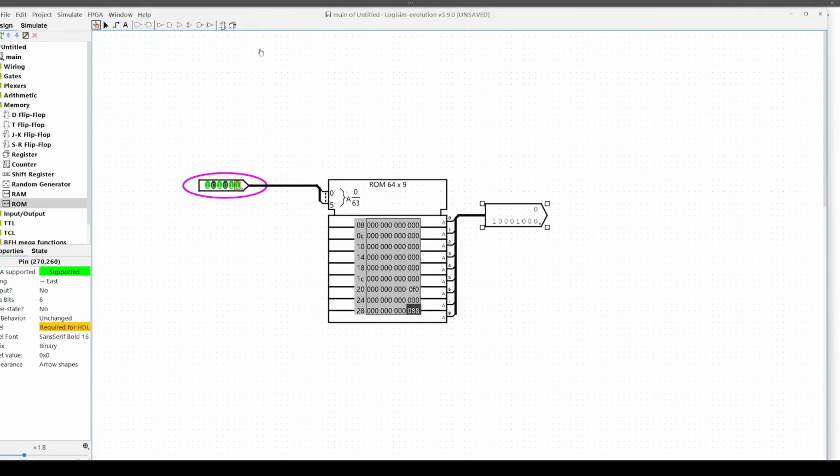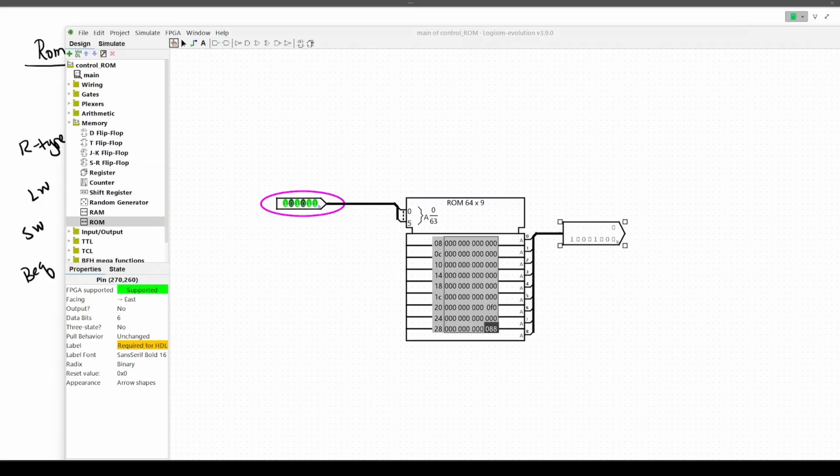As you can see, we have implemented our control unit. Very simple. No need to stress about gate implementations. It's just pure microprogramming, and it helps a lot, and it will help us expand our project later on without much of a hassle. Well, now that I have implemented the control unit, we can start wrapping things up. Today we saw how a handful of bits can drive our entire data path. With our implementation using a ROM, microprogramming becomes straightforward and extensible.